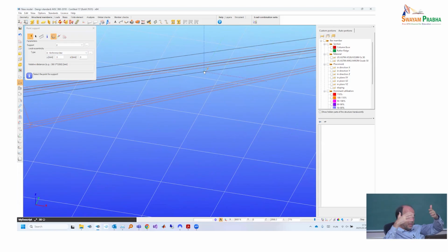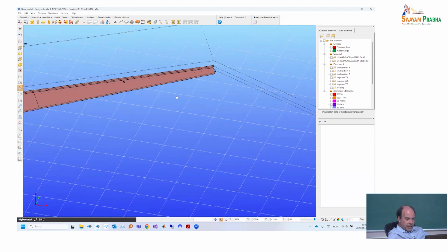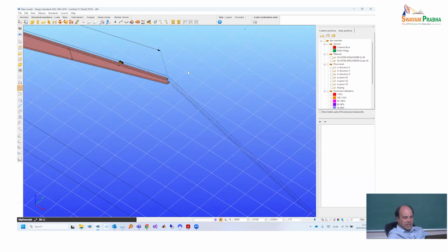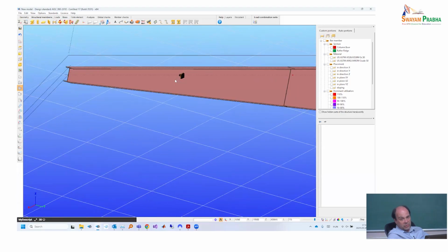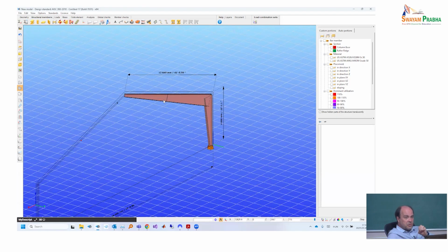So this is my reference line. This is the internal, the inner line, which I finally managed to do with quite a lot of CAD functionalities. This is the reference line of the members. If I don't define any additional eccentricity, then every object which is attached to the member will be positioned to this line. Now that's not what I want. It's even better visible if I change to the solid representation and look from behind, and then it's really visible that the support is not attached to the upper flange. That's not what I want, so now I delete it, because I will need to define not just the position, but also an eccentricity.